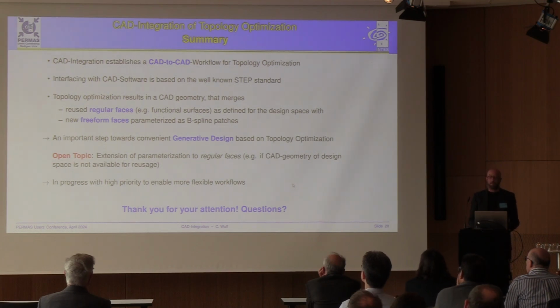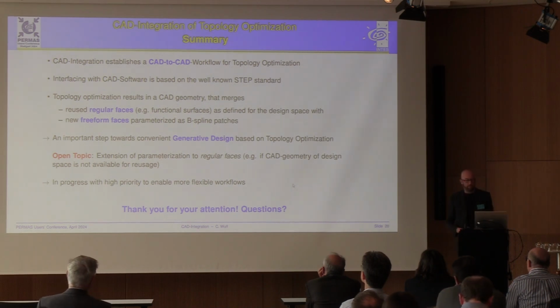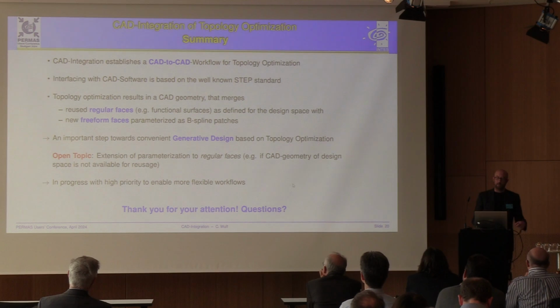The CAD integration that we implemented established a CAD-to-CAD workflow for topology optimization. This means we start with a CAD geometry of a design space, and the result is a CAD geometry of the final design. The interfacing with the CAD software is based on the well-known STEP standard, and the topology optimization now results in a CAD geometry that merges the reused regular faces from the original design space geometry together with the new free-form faces that are parameterized as B-spline patches.